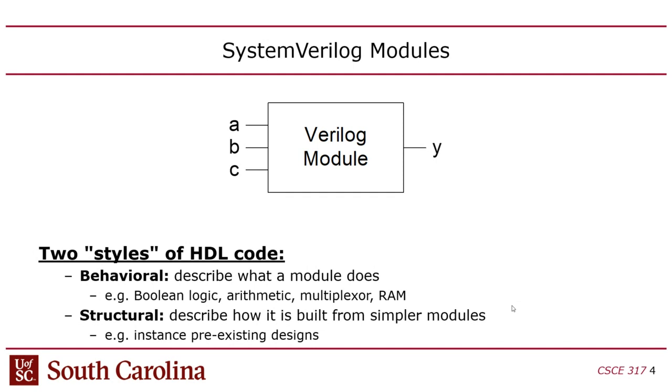Like if you have a memory and you want to say, I have a memory and it has 4 ports, and it has a 1-cycle read latency. That's basically behavioral description. And then there's structural descriptions, which is where you essentially describe an interconnection of modules like a schematic using Verilog, literally just describing a graph of instance components and how they're wired together.